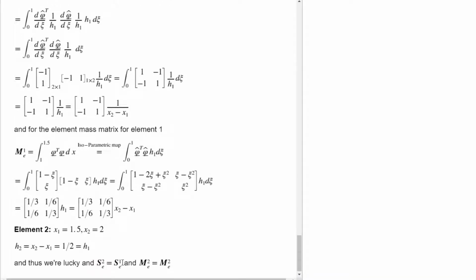So every matrix, as long as our mesh has the same length, all of these stiffness matrices and mass matrices are going to be the same. And that's really not the strength of the finite element method, because as we will see when we do the assembly shortly, this method that we're using here now will yield the same sort of matrices as the finite difference method, but the finite difference method can be created in a much more efficient way than what we're doing here.